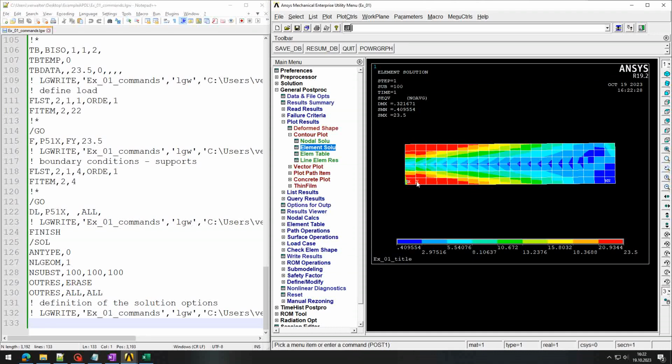The plasticization is happening at this point a little bit, but we have not reached the full plastic capacity of the section. Why? Because we have this interaction between bending moment and shear force. So in order to find the maximum load, we can just increase the load and then see how that works. So I'm going to stop the video here, but I'm going to proceed with the next thing in another video.